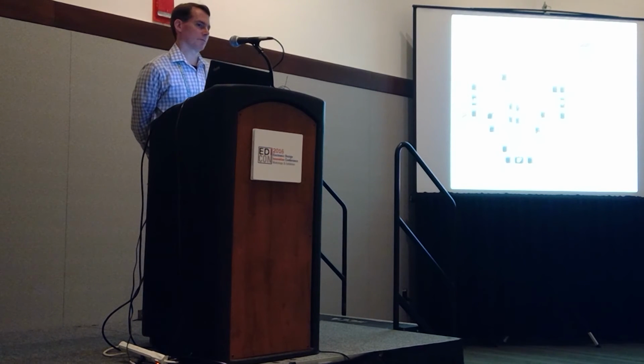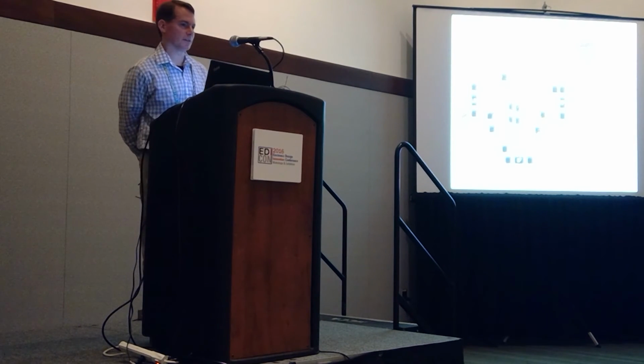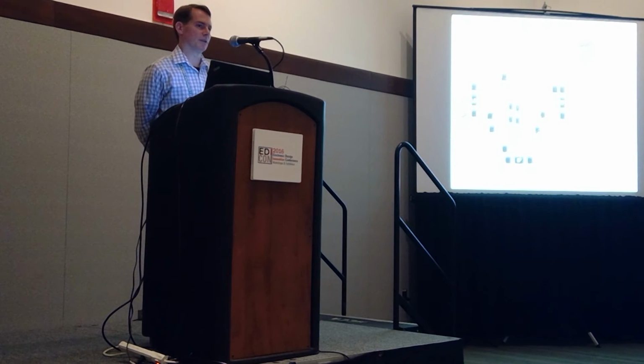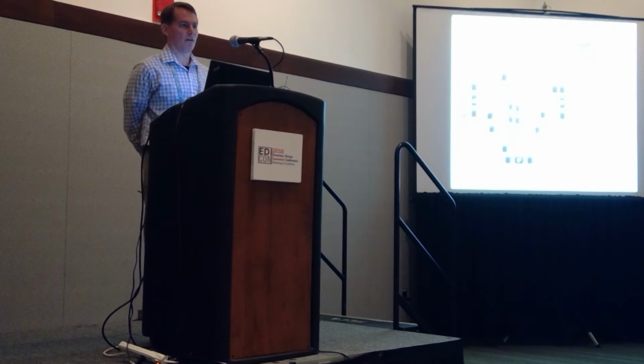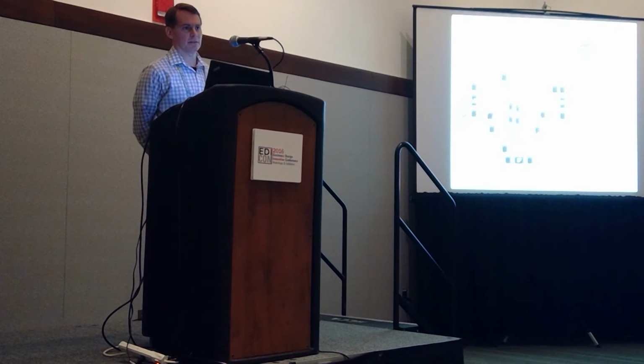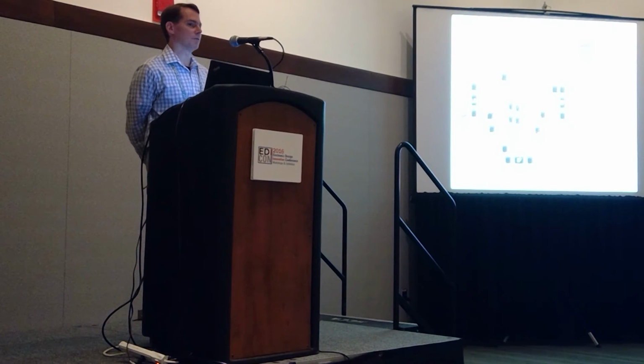The question is how much. We certainly know that the phase noise of gallium nitride amplifiers is not as good as something like an HBT, and you're going to see that in the mixer. But in some cases, it's still okay. In some very high precision applications, you need that low phase noise, and gallium nitride in general is not going to get that for you.